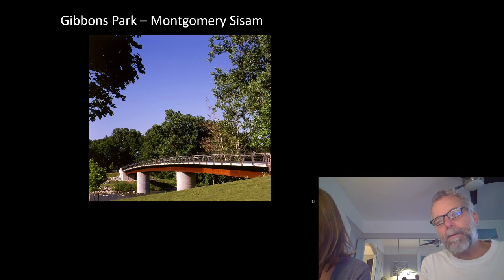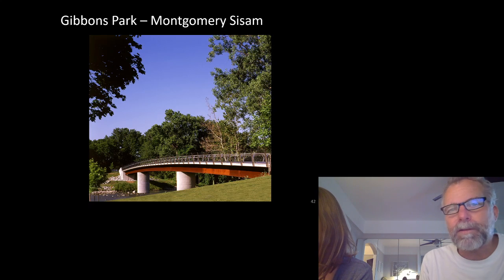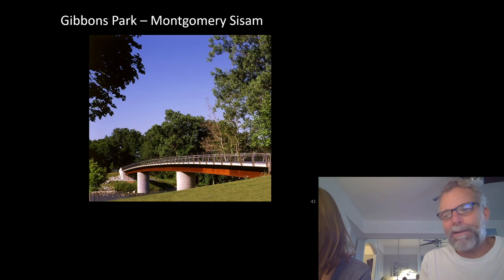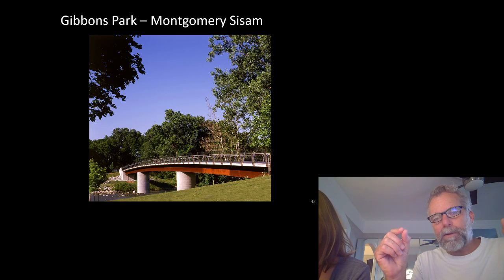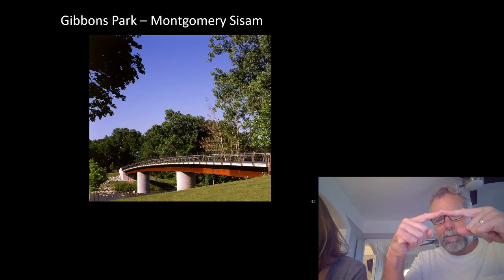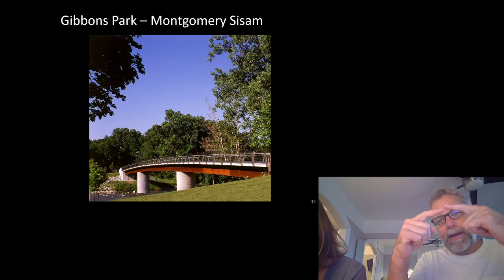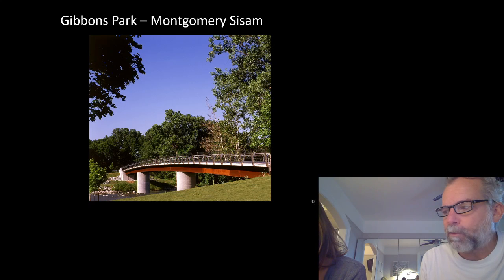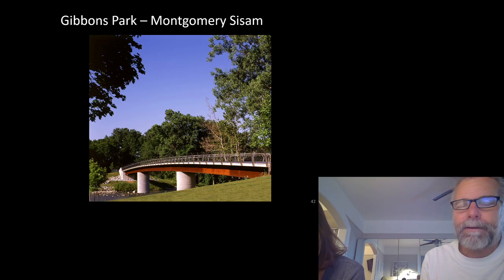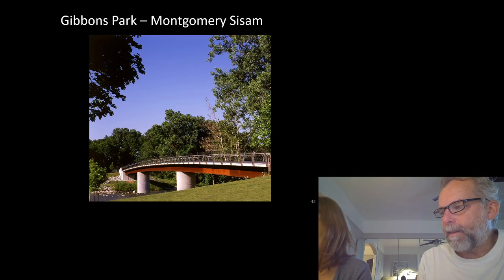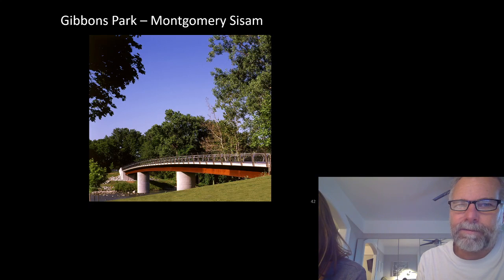So, a simple span bending moment diagram: the peak bending moment is WL squared over 8. If we introduce continuity over the supports, so we don't let it hinge at the support, we wind up with a hogging moment, a negative moment over the support, and the peak moment at the support is now WL squared over 12. So it's 50% less than, or a third less than, the moment that you would have in a simple span.